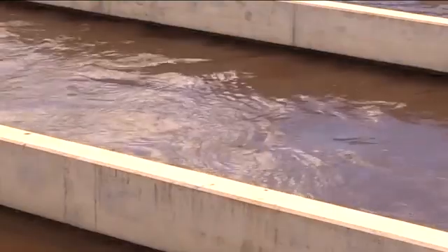Equalization facilities consist of a holding tank and pumping equipment designed to reduce the fluctuations of the waste streams. The equalizing tank will store excessive hydraulic flow and stabilize the flow rate to a uniform discharge rate over a 24-hour day. pH adjustment. A pH adjustment is carried out after preliminary treatments in order to obtain a wastewater much more suitable for the biological processes following, in general in the neutral range.